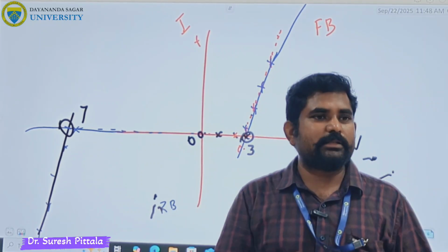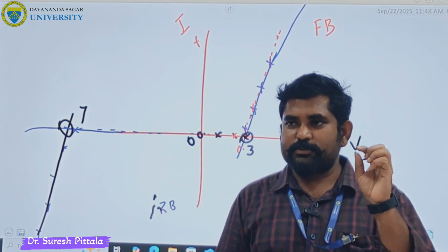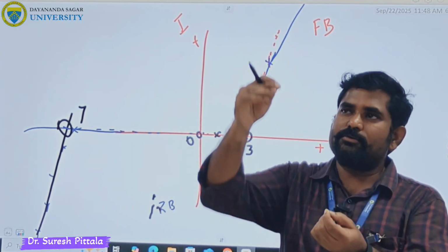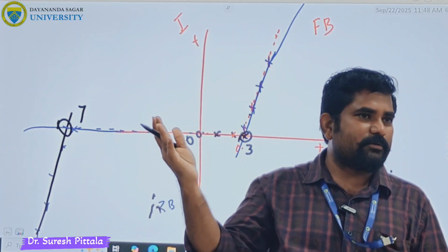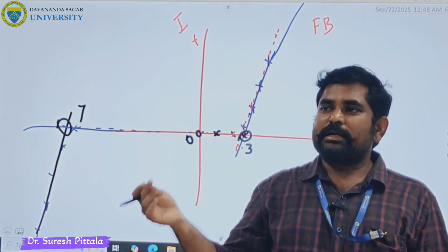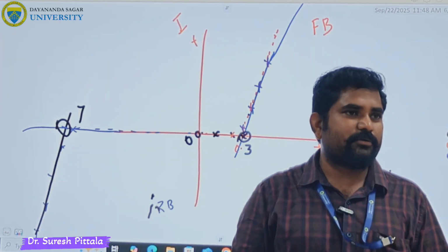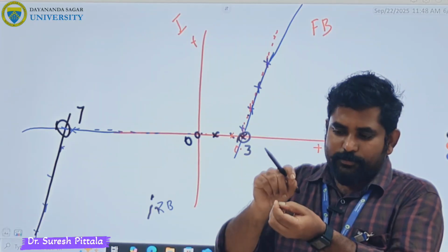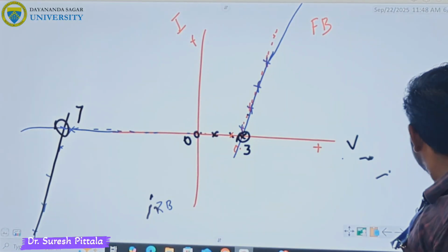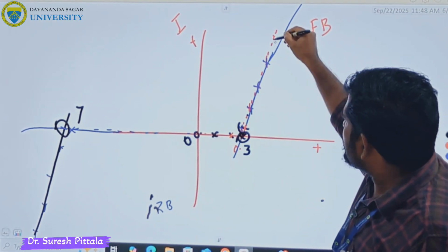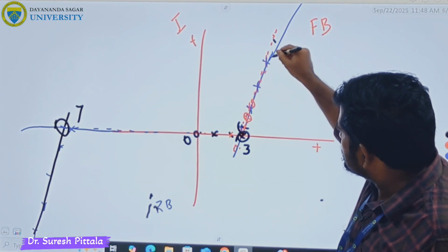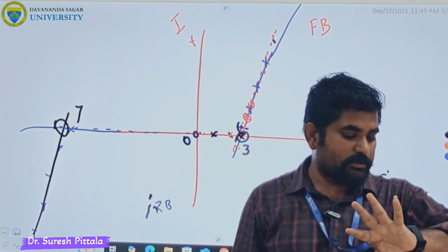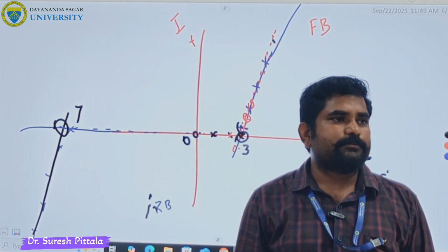But in the table, while taking the readings, take as many points as possible. Up to 20 milliampere, don't start with 1, then go to 10, then 20 and be over. Only 3 points you would have. Not like that. If you can manage to take 10 readings between 1 and 20, hats off. 20, even more great. Take as many readings as possible. Look at the current and maintain the gap between these points as small as possible. For that, you have to increase the voltage as smoothly as possible. Understand? So this is the Zener diode experiment.